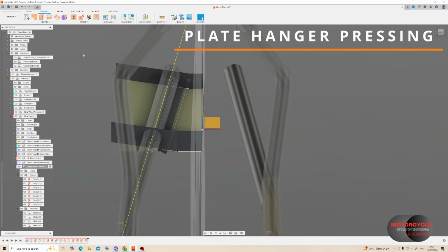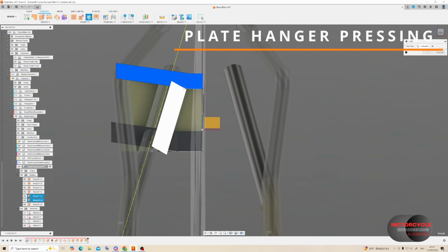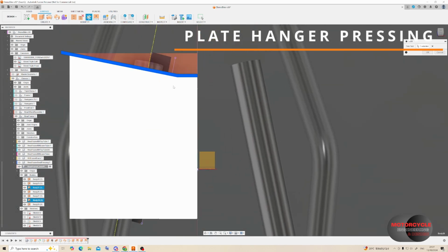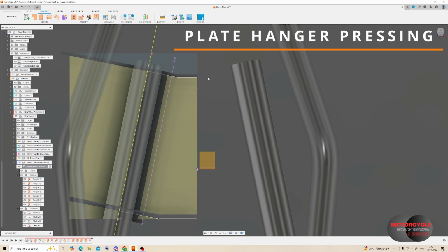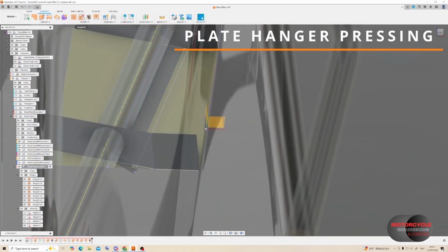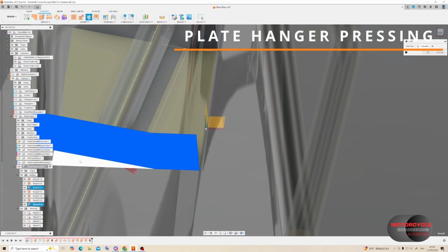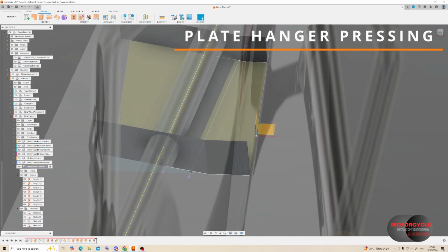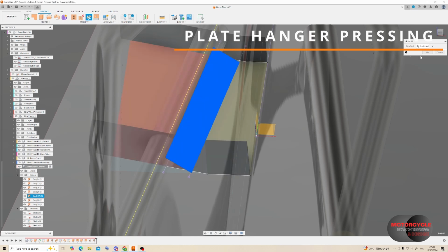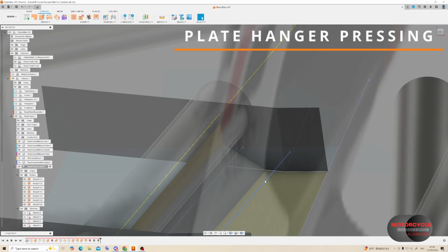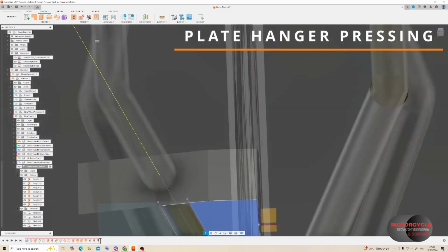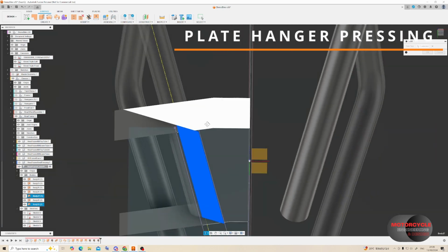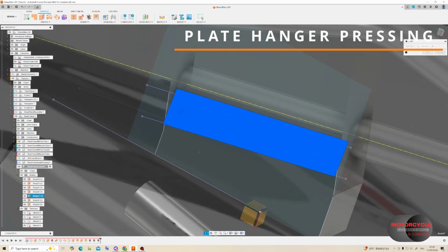In addition to the bodywork around the end of the rear frame, there's also going to be some plastic infills or plastic moldings which are going to be there to help support other electrical components, maybe the battery, the fuses, ECU. So we're going to have to take that into consideration. With any pressed features that we add in here, it's going to interfere with the packaging space that we have. But we may also need to include some extra fixing locations to help support that load. So we have enough material in this bracket, in this pressing, just in case.